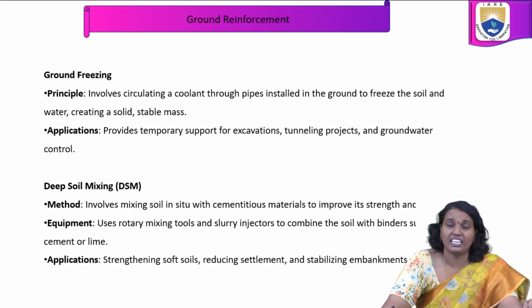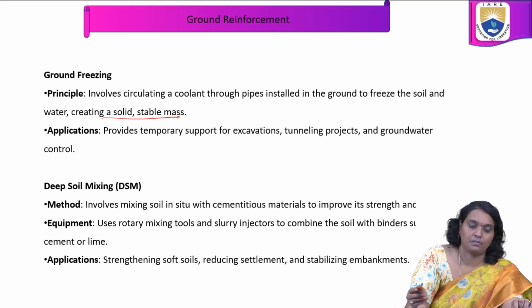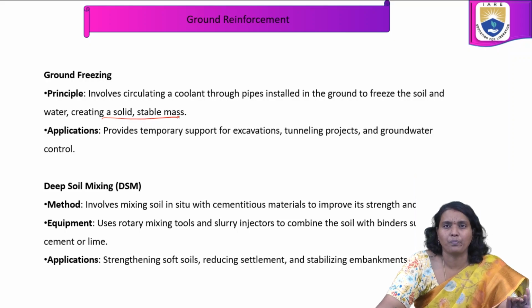Ground freezing. In this, the principle involves circulating a coolant through pipes installed in the ground to freeze the soil and water, creating a solid stable mass. It provides temporary support for excavation, tunneling projects and groundwater control.